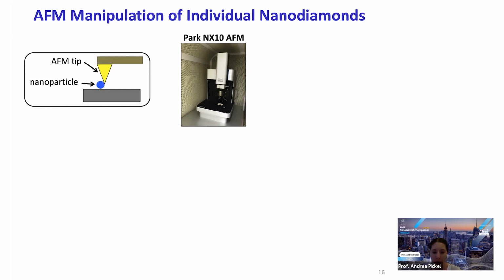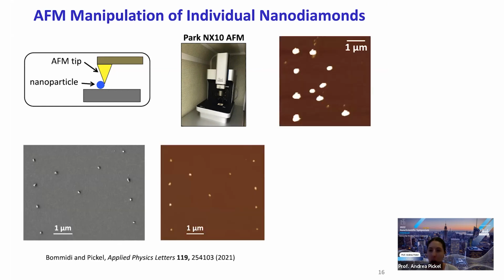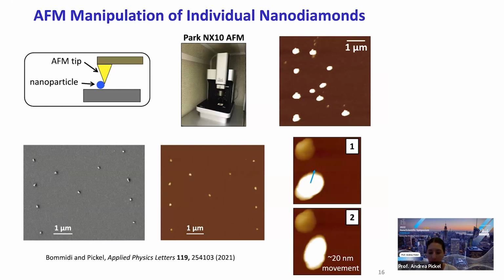And as we've sort of heard from others, we do this by essentially hacking the nanolithography mode of our AFM to move the nanoparticles along the desired trajectory. So with this approach, we can make microscale movements, which is how the patterns that you see here were formed. But then we can also do much finer movements, so easily down to tens of nanometers.